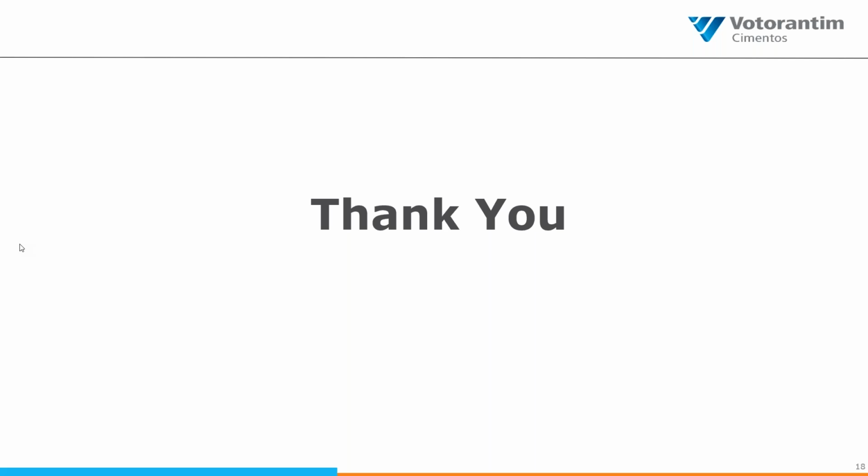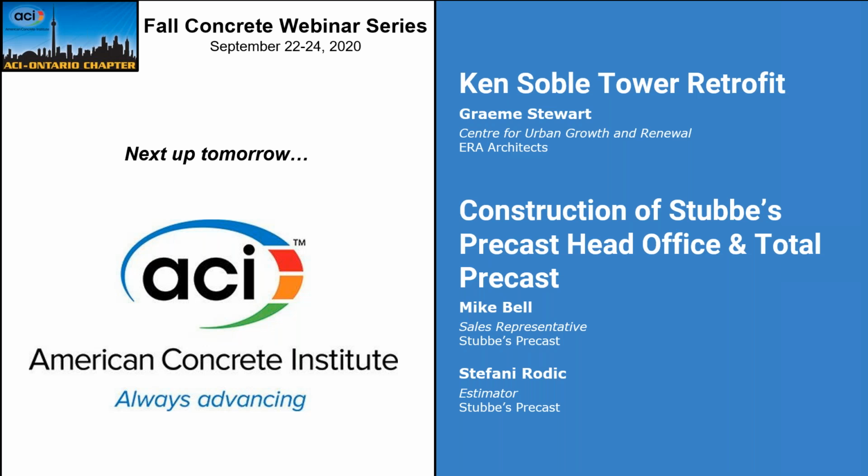Yeah. Fortunately for us, we have never had an in situ incident up to this point. It is a major concern for us because along with aligning the cylinders and what we could possibly do, we are not confident that if we had to take cores from an in-place form, that we would be able to accurately or satisfactorily even run a test on that. So we tend to run these mixes with a lot of either viscosity modifier or retarder just to help hold that paste very robustly to minimize any sort of aggregate segregation.